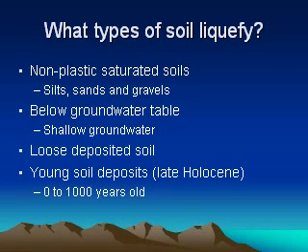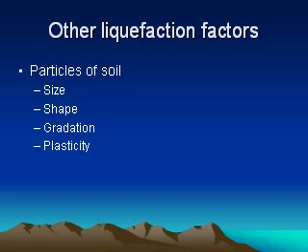And young soil deposits, such as the late Holocene deposits that are anywhere from 0 to 1,000 years old, haven't had the time for the structure of the matrix to settle, and can be more susceptible to liquefaction. There are other factors as well, such as the size of the particle. If the gravel gets too big, the weight gets so big that you're not going to get movement of the soil, so liquefaction is not going to be possible.